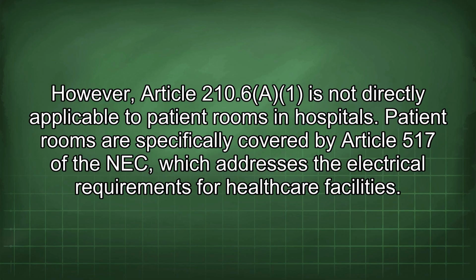However, Article 210.6(A) is not directly applicable to patient rooms in hospitals. Patient rooms are specifically covered by Article 517 of the NEC, which addresses the electrical requirements for healthcare facilities.